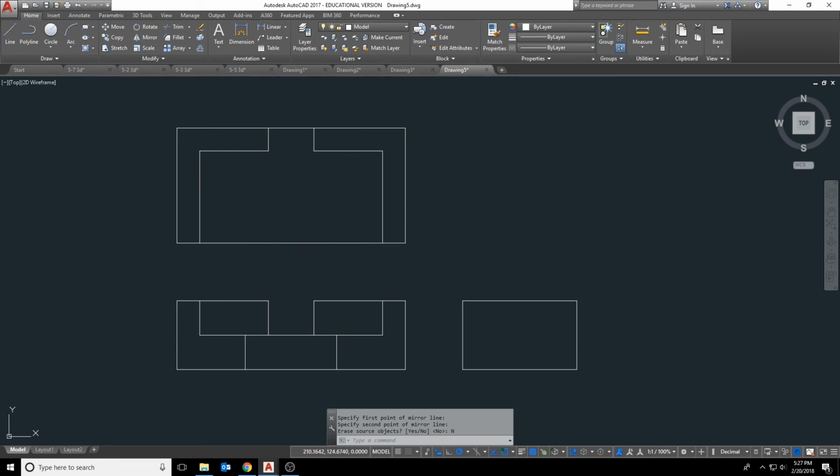Now I can put in the cutout that goes in the front. So we'll come in here, project a line up, this goes back 25, and it comes over to this point here and then closes off. And now I can go to the trim command and get rid of the front of that shape. Now, one thing that you're going to notice in the book, it is not drawn proportionately. The dimension for this is 25. The total depth of this is 50. And in the book, it doesn't look like it's quite that deep, but we can see here that it is. So the right side view is complete minus the hidden lines.